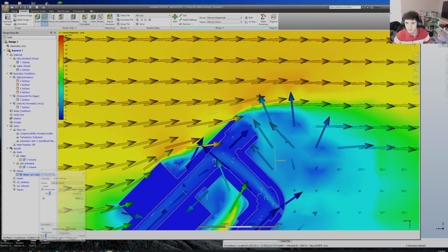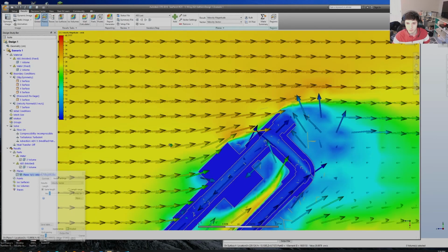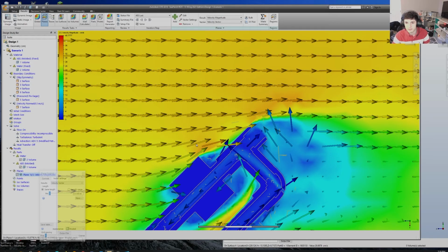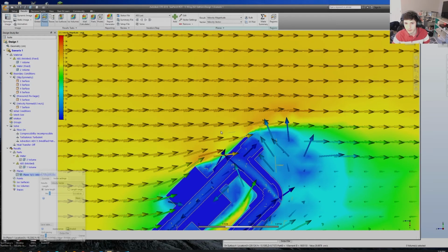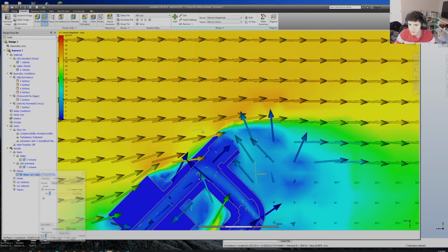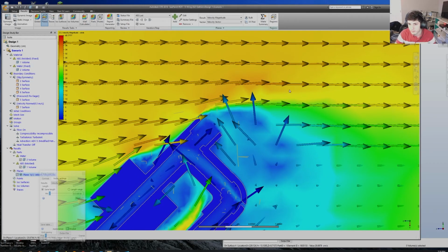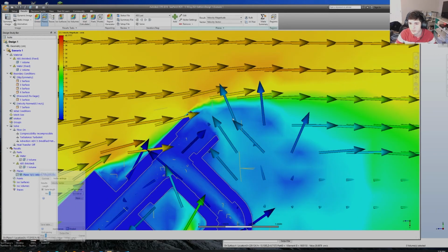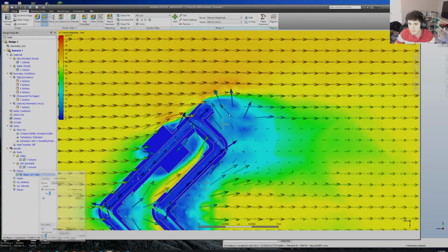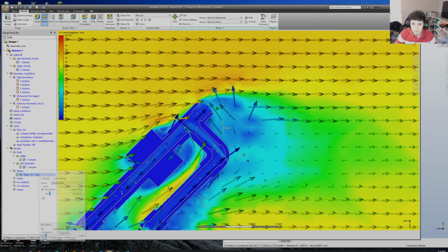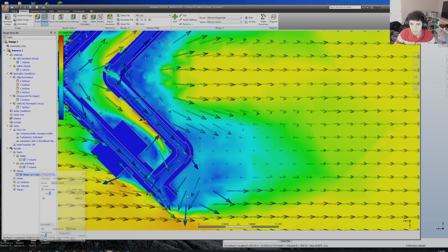And you can see how this water that's moving faster around the outside speeds up because the water moving directly on the outside interacts with the water moving farther away from the outside of the ROV, which causes the pressure to increase in this area and also the velocity to increase, which is why you see more red right here and why you then see some blue right here too. So this right there is an example of a turbulent wake, and you can see the same thing on the other side.